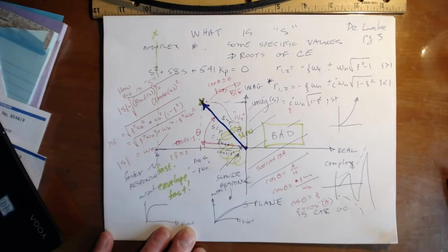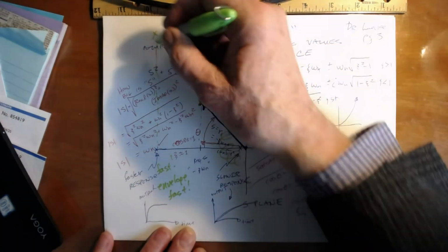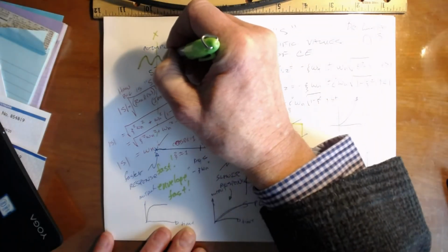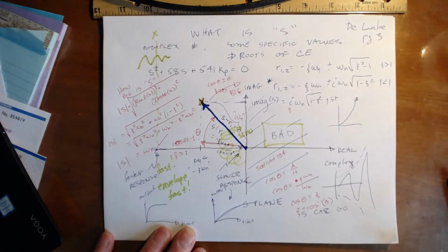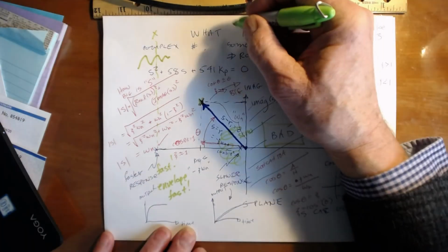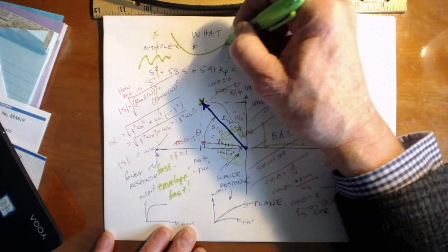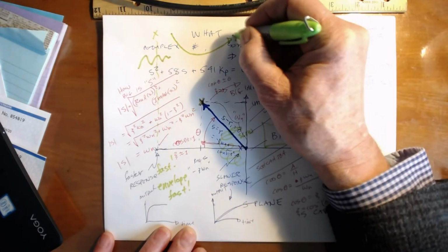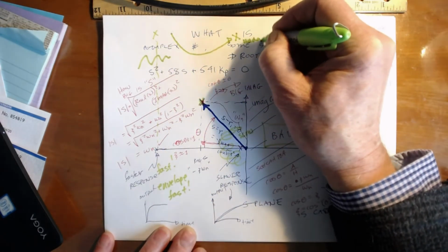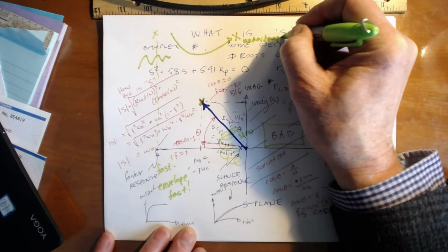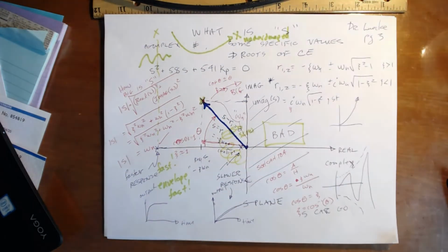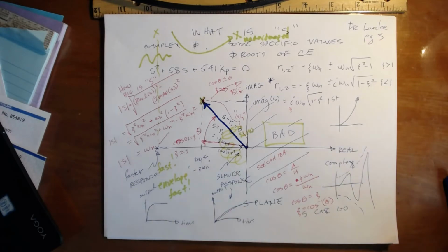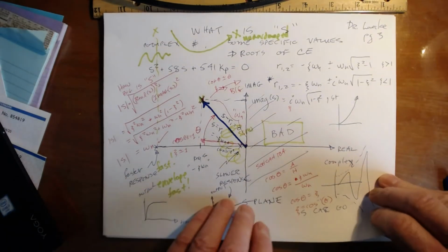And they might oscillate with some damping ratio. We can tell what the damping ratio is. Moreover, if things get way over here, these are way underdamped. So without any more than that, you tell me what the roots of the characteristic equation are, and I can give you some information about what the response of that system is going to look like. And that's important. Okay?